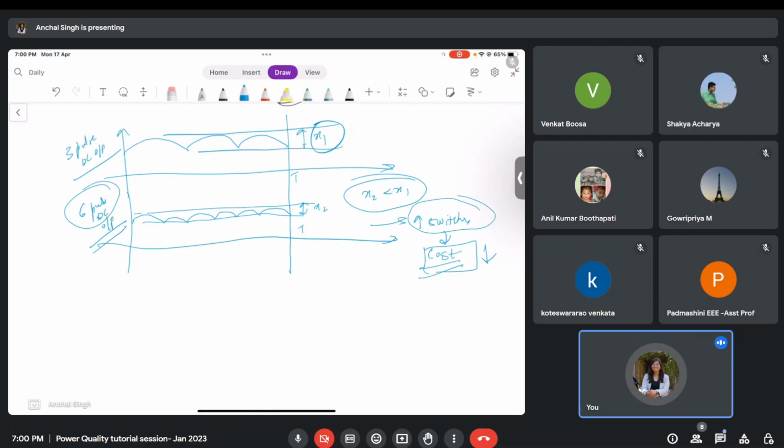So depending on your application, if I am using medical equipment, then I don't want any kind of spikes to manipulate the readings of my patient. Therefore, in medical equipment, I will use a very steady and pure form of DC supply, and that is the reason medical equipment is very costly. You cannot say that electricity went and the readings are not there with you. You have to connect a UPS, an uninterruptible power supply backup, for every critical equipment. Then you have to put in a pure DC power supply so that there is no noise in the output result.